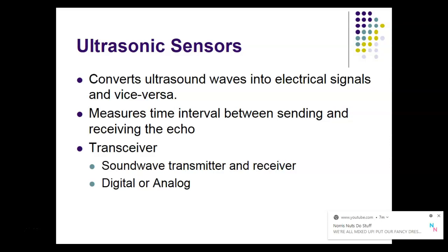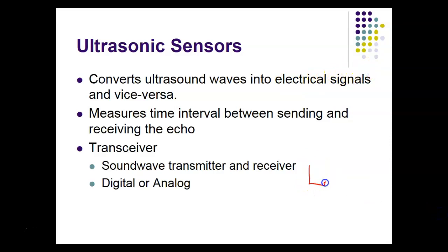So these guys can be digital or analog. They can be diffused, which means it actually bounces off the device, or it can be direct. Direct means you would have the transmitter and the receiver separated, so it works like a direct scan. On that one, you're blocking the beam. And diffuse is what we see most of all, where it literally comes back and hits the object, and then it counts how long it takes to bounce back. And these guys are very precise.